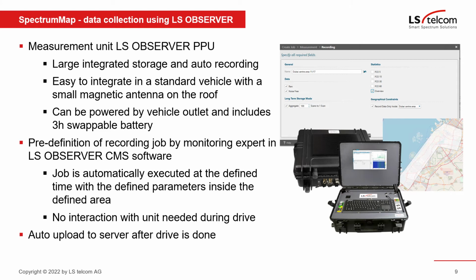So as a user, in the LS Observer CMS software, where you can control the units, you simply define the area for the recording, you define the measurement parameters like frequency range and further receiver parameters, and then the recording job will be automatically initiated once the driver reaches the area which you defined here.